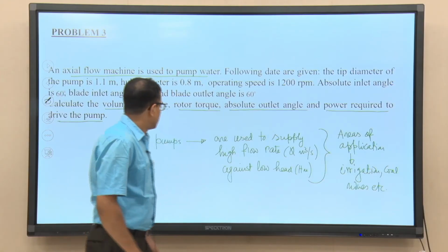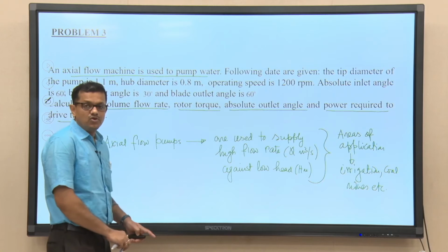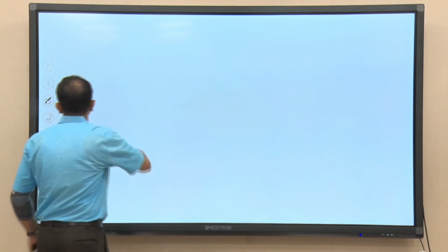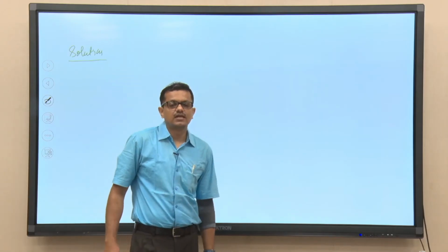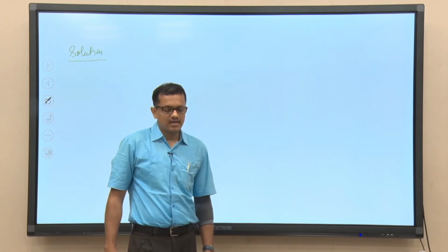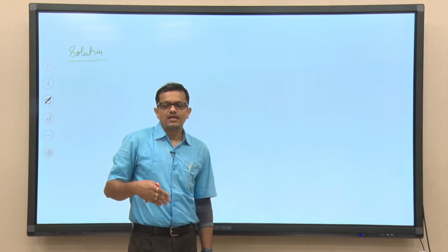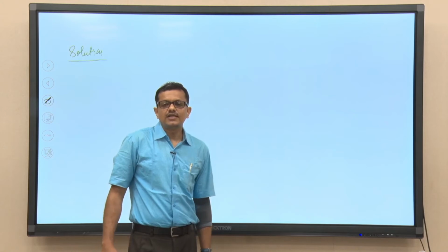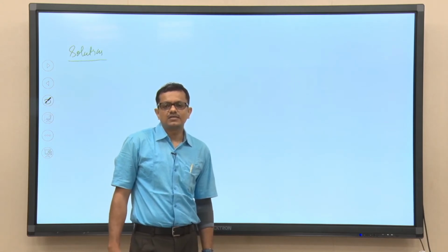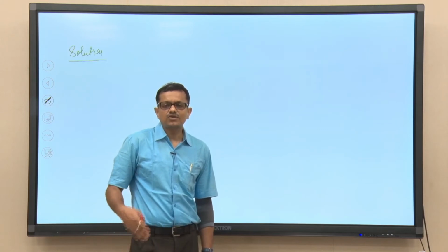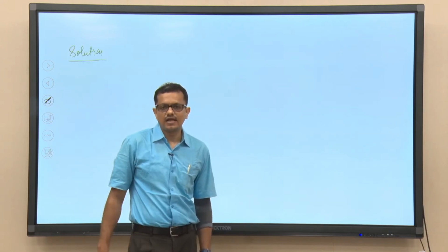So, with this brief recapitulation, let us now move to solve the problem. Again I am telling, in line with what I discussed in the last two lectures, that before solving any problem related to a pump, whether it is a radial flow pump or an axial flow pump, our first objective should be to draw the velocity triangles.